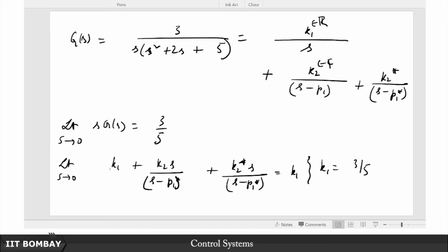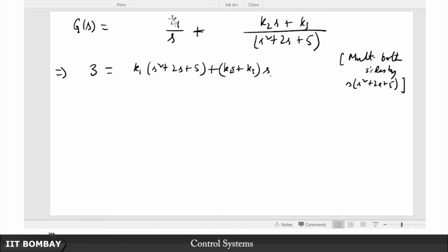So the trick I would like to point out here is, if you have a combination of complex and real poles, first multiply it out with real poles one by one unless they are repeated, and then you see what those coefficients of the real expansions are, that is in this case this K1. Then you multiply by the overall denominator and equate coefficients and use the fact that you have already determined what K1 is. Of course you can just equate from both sides here and you will get K1 plus K2 is equal to 0, and you can pretend that you do not know that, but we do not need to pretend that, that is my claim, right.